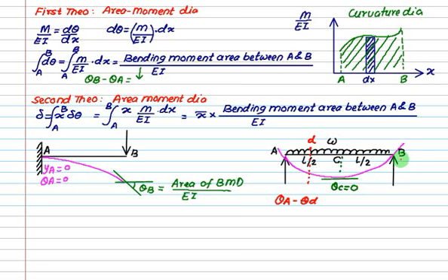There is no deflection on this side as well as no deflection on the A side, so naturally it will deflect more at this bottom point. Where it is more, naturally the tangent to it will have a slope equal to 0. Is it correct? So for a simply supported beam, the slope at the center will be 0, and for a cantilever, the slope at the fixed end is always 0.